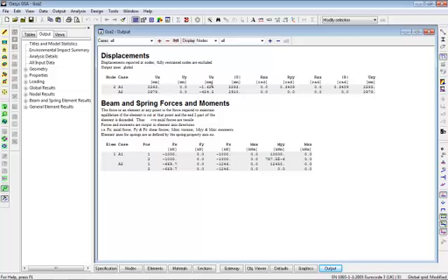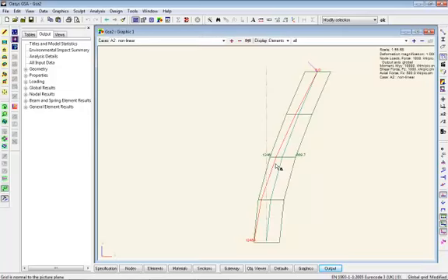We can see that, for example, the non-linear analysis, we're getting quite a large vertical deflection, as well as quite a large horizontal deflection on that top node, and we see the axial load is reduced, the shear force is increased and the moment is increased on the non-linear, because basically it's moving so far away from the original that the linear analysis just is not going to give the right answers anymore.